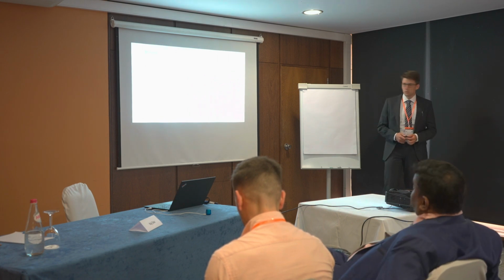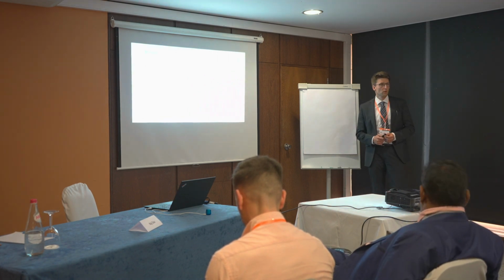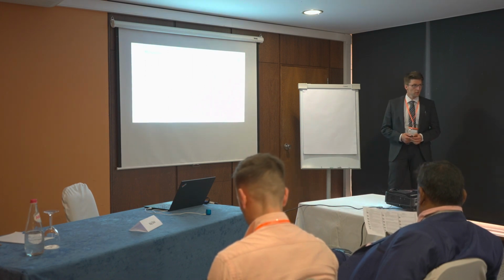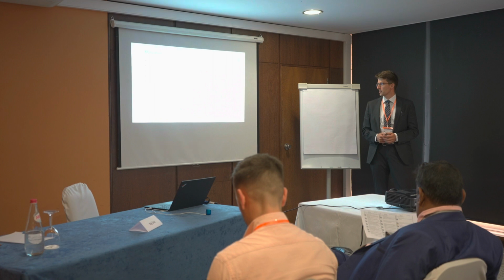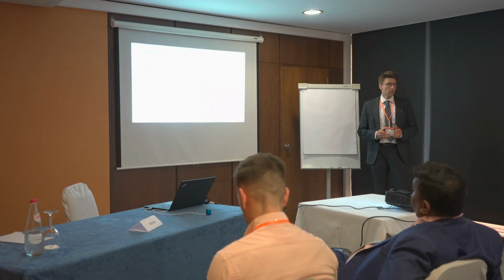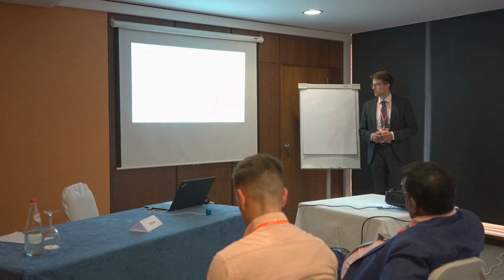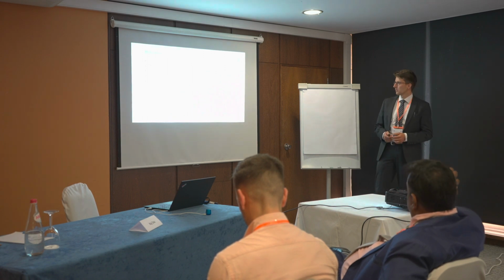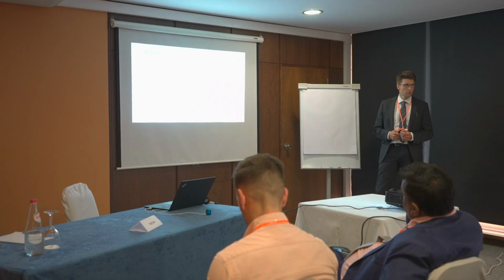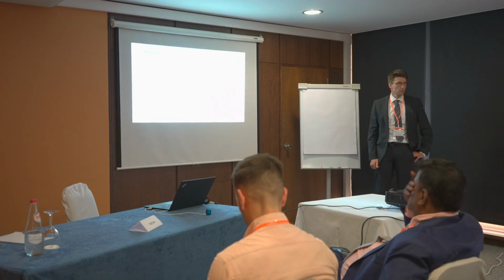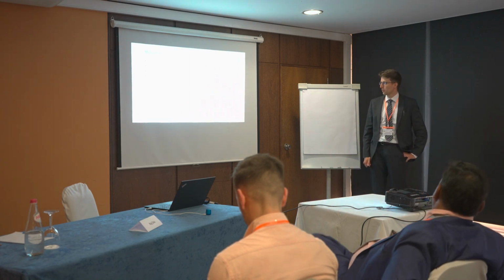So, as you may know, the split Hopkinson pressure bar, also named the Kolsky bar, is used for high strain rate testing, for example, for compression tests. There are long, slender bars. These deform elastically, and the elastic deformation should be evaluated by using strain gauges. And these strain gauges need to be calibrated, and we do it in a dynamic way.